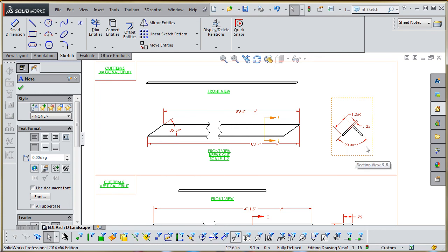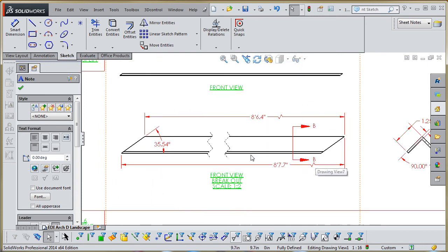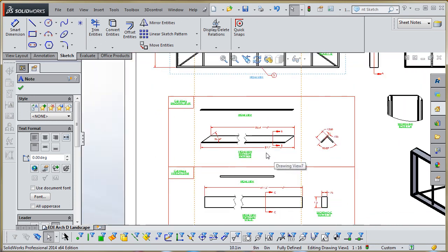I don't know what the size of the pieces are here, but those modifications can be made and changed. But again, this is just a concept, you might say. So it gives you the overall length here, so you know that at least 8'7" and maybe 3/4 of an inch size piece here with these 35.54 degree cuts in here will result in this piece that you see here.